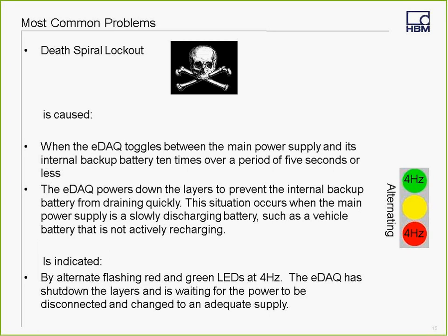This situation occurs when the main power supply is a slowly discharging battery, such as a vehicle battery that is not actively recharging. It's indicated as shown here by alternating flashing red and green LEDs at 4 Hertz. To summarize this fault, if you receive it, there is something wrong with your power supply.